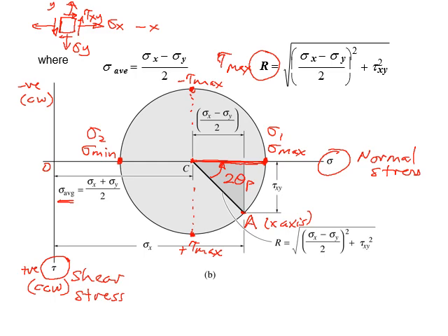So what it says here from the graph is that the axis for principal stress 1 or maximum normal stress in this diagram here is counterclockwise from the x-axis. How much it changes is given by this angle, so it's 2 theta p. So if we draw x, right? Therefore, x prime, that line there, is counterclockwise, and the angle is theta p, half the angle in the Mohr circle.